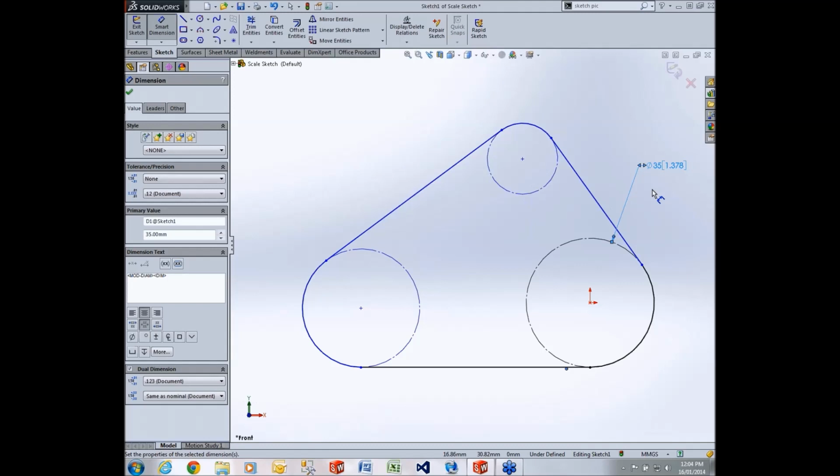So what's actually happened in the background is that it has changed the size of that circle, but it's also scaled the rest of the sketch down with it, and then changed the viewport's zoom level so that nothing appears to change. This is one of those things I was talking about where there's a big focus, because new users wouldn't even know how it used to work. But for grizzled old SolidWorks users like us, we understand what a boon this is, to be able to rough your sketch out without having to care how large the actual sketch is, and then to have the whole thing scale for us when we apply that first dimension.